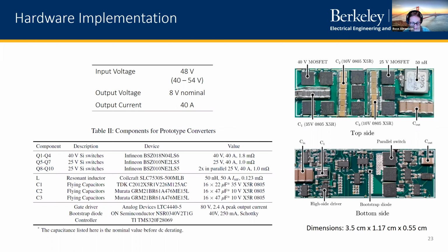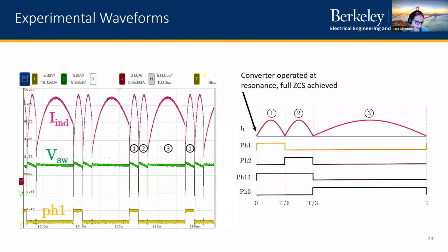So these are not C0G capacitors that have to be very big. We can just use standard MLCCs, and we don't actually care what the exact value is, as long as it's big enough. So it's more like matching a margin than matching an exact value.